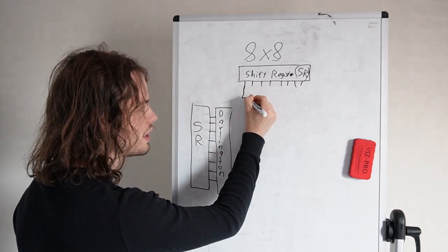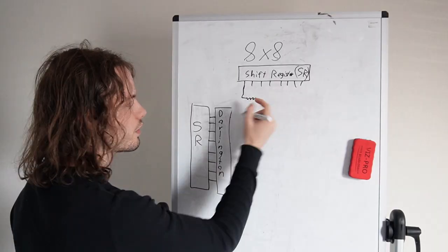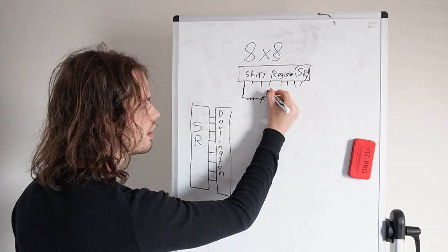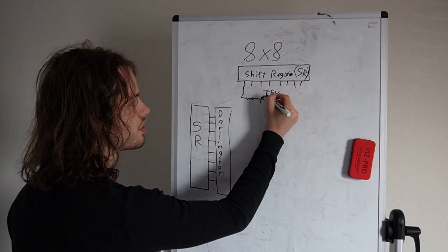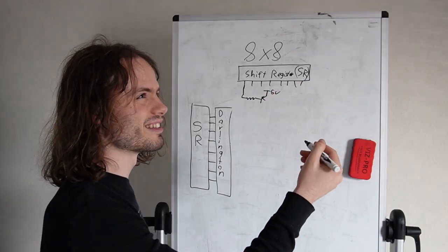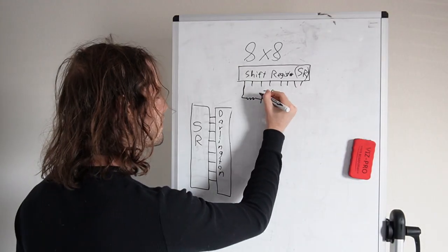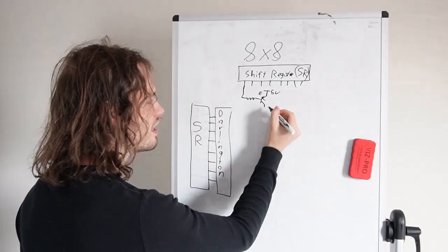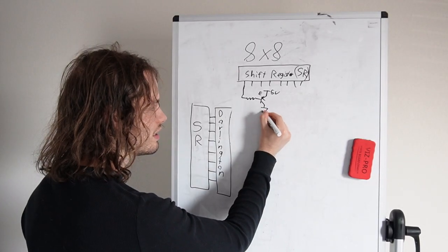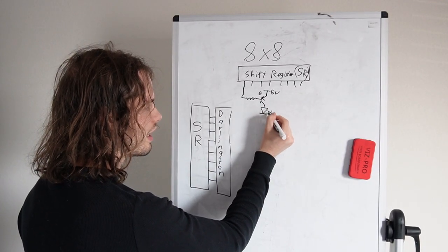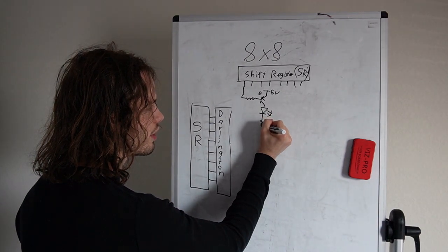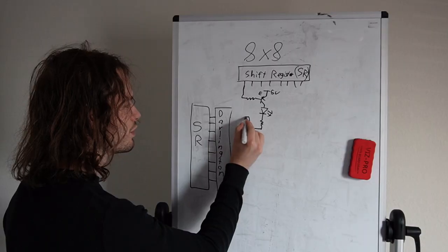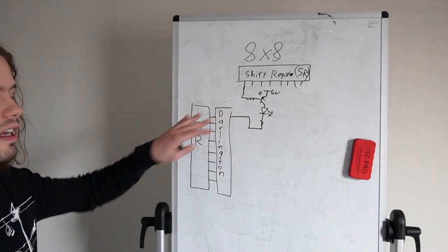What it'll actually be is a resistor into a PNP BJT, which has its, what is it, its emitter and collector. Its emitter is connected to power, and its collector is then connected to an LED and another resistor to limit the current. I went a little past it, but this would then connect to the first element there.